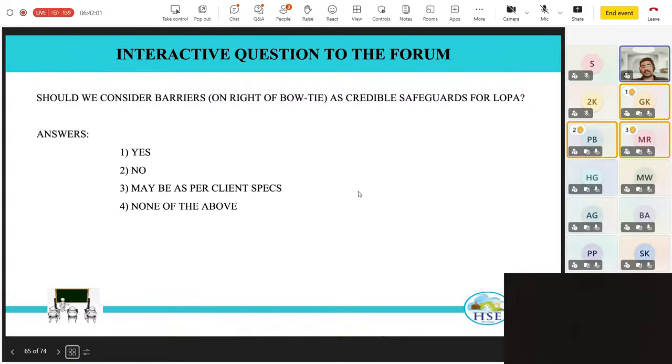However, consider the same setup, same two tanks, with a pump in between, an ESD at the inlet of the second tank, and a fire and gas detection system with another client, who has designed a system to be very conservative or impeccable with high integrity and a good system. So what he would have done is use the same fire and gas detection signal to isolate the second tank by closing the ESD valve, because you don't want to add fuel to a fire scenario. So that is conventional design, or it should be. It is a good design practice.